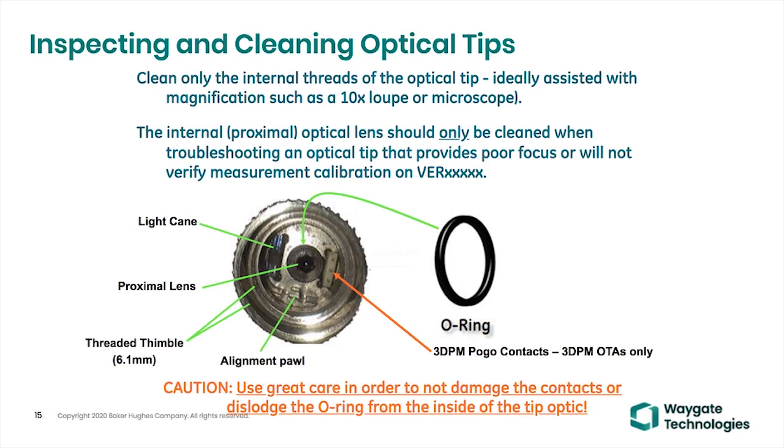If for some reason you've been working in, and this happens a lot in wind turbines, meaning the lenses and cameras are exposed to oils that are not easily cleanable with alcohol, then you'd want to use that same dish soap method where you put a couple of drops of dish soap that professes to have degreasing capabilities and swish it in the soapy water, take it out and put it in clean.